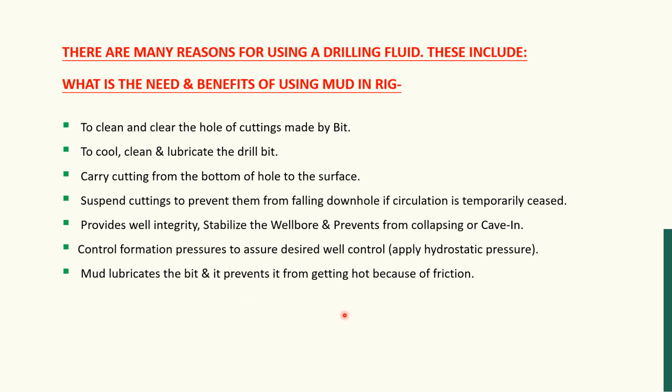The second reason is that the drill bit and the drill string are mechanical equipment. When drilling starts, it goes on continuously for 24 hours, as long as we don't reach our desired depth. So due to the continuous operation of the mechanical equipment, the drill bit will get hot. So the drilling mud lubricates and cools, and doesn't let the drill bit or drill string get hot.